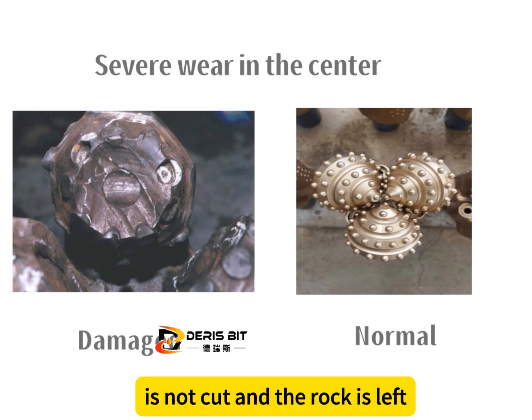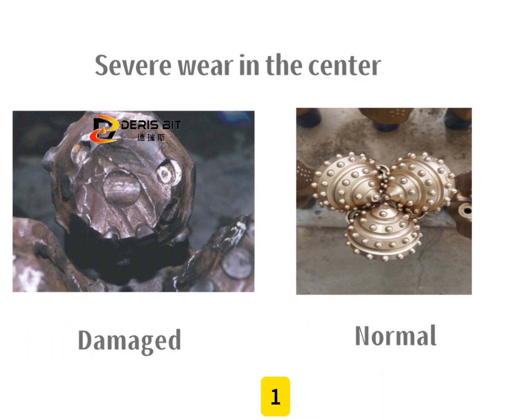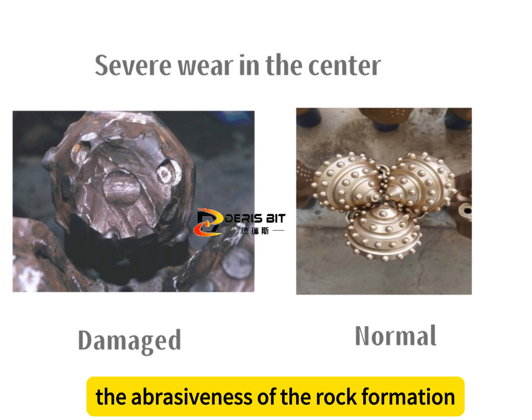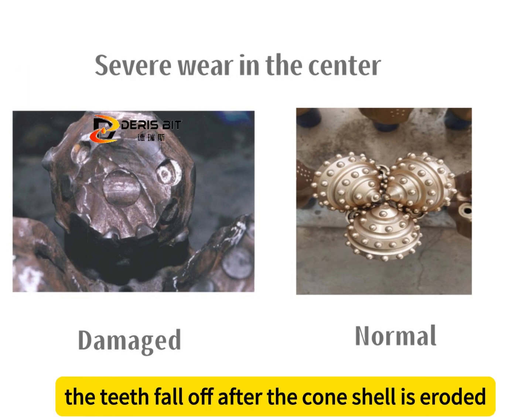6. The center of the drill bit is worn out. The teeth in the center of the drill bit are worn or broken, so that the corresponding formation at the bottom of the well is not cut and the rock is left.